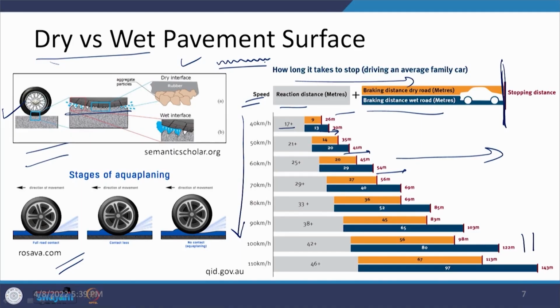There are going to be protruding items, maybe aggregates coated with bitumen, providing this type of surface, and when the wheel moves over it, it contacts those aggregates at certain points, and at some points it may not be contacting. You can see that at this point or at this point it is not contacting, but at this point, or when the pressure is lower and the contact area is increasing, we found that in this particular area there is a complete contact of the tire with the pavement.